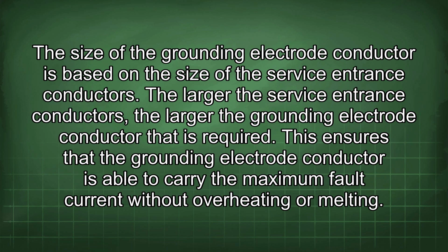The size of the grounding electrode conductor is based on the size of the service entrance conductors. The larger the service entrance conductors, the larger the grounding electrode conductor that is required. This ensures that the grounding electrode conductor is able to carry the maximum fault current without overheating or melting.